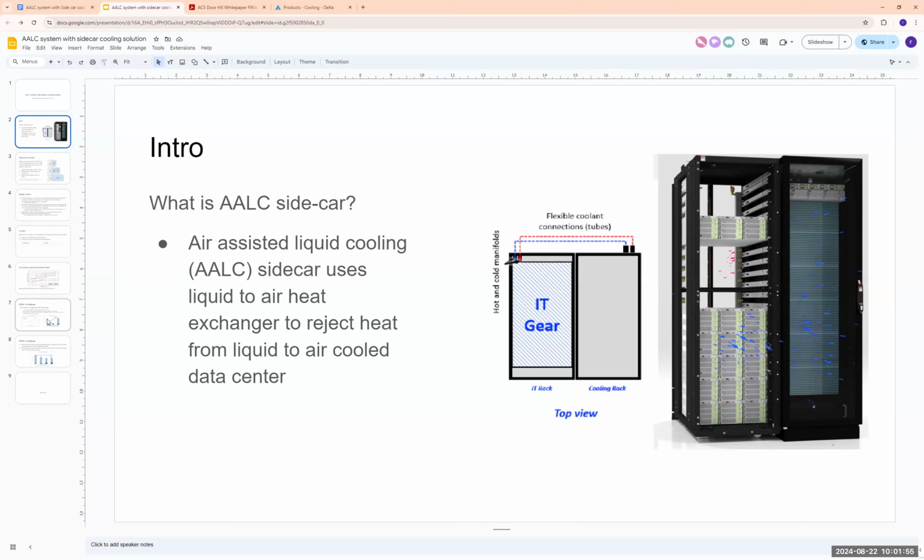Okay, so that's exactly what needs to be in this presentation then, is that we have two critical points. One is we've got some upper limit of cooling capacity for a rear door heat exchanger, and when you cross that, you need to go sidecar so that you can have physically a larger heat exchanger. But then, now you've sold me on sidecar, and the next critical point is what the TPD is of the chips that I've got.